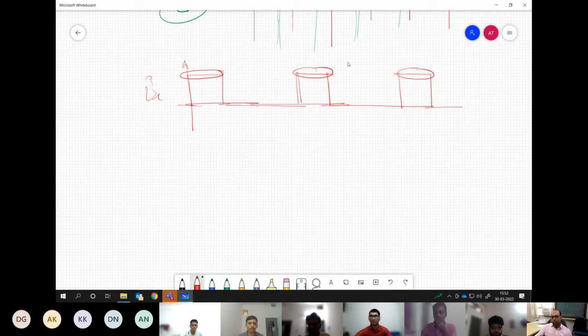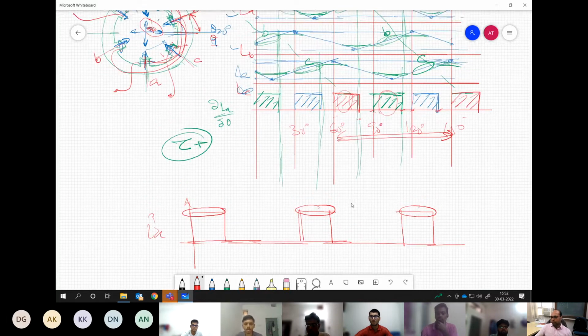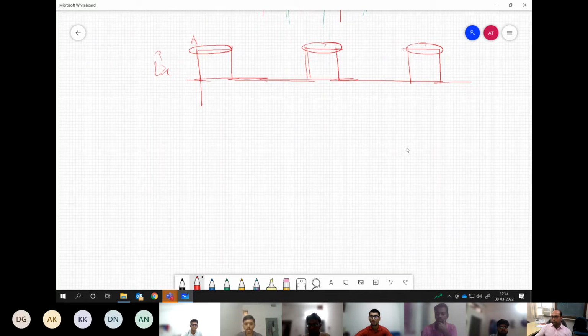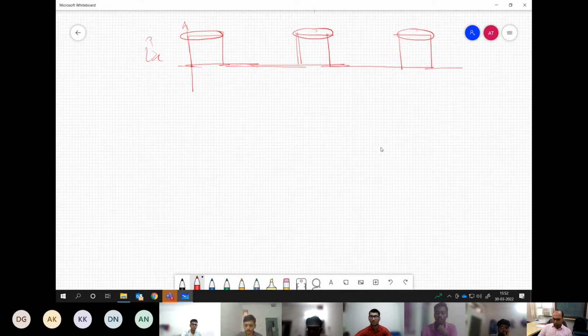You have understood the machine, but now you have to run it. You have to control it. For that, we have to inject constant current pulse. So how do we do that? What's the way? By using H bridge. Yeah, that is one correct answer. But H bridge is just connected across the device. How do we inject? By that I mean, what is the control method by which we are doing this? Okay, so this answer is okay for starting.